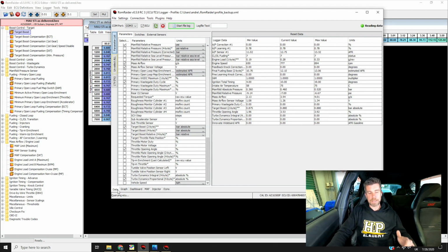The other aspect is that we want to be really smooth with our throttle application. So particularly if we are scaling our mass airflow sensor or those load compensation tables that we looked at, we want to make sure that we aren't being aggressive or erratic on the throttle, because this is going to bring in transient enrichment, and that's going to generally result in data that's not that meaningful. So really nice smooth inputs.